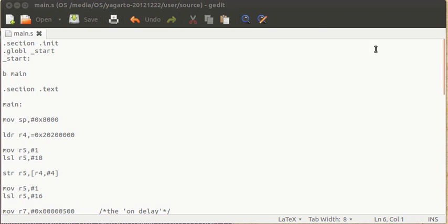And last thing before we get started into the code, I just want to discuss the concept of duty cycle. This is simply the percentage of the time the load is receiving a current. As for the LED, as the duty cycle decreases, it's receiving the current a smaller percent of the time, and we'll see it as dimmer. I might just use this term as I'm discussing the code. So I'll just hop right into it.